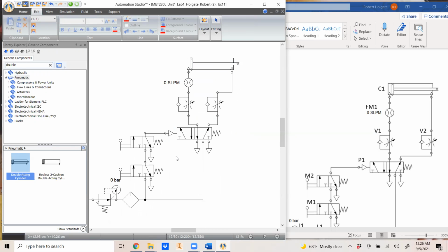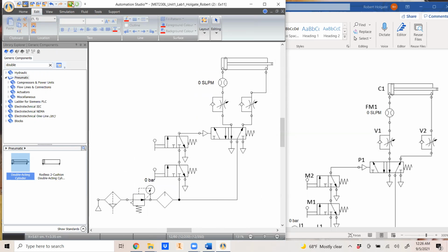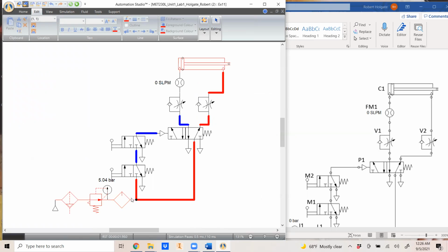So let's check that the levers work, that it sends an impulse the right way. Let's simulate. Pressure's coming in, it's getting stopped at this normally closed lever. I can push it, but a lever now will stay. It's kind of like a detent button, but my lever is going to stay. I shifted the lever over. Now it opens flow, but I can't cause an impulse and make this cylinder extend until I have two. And then it will extend.